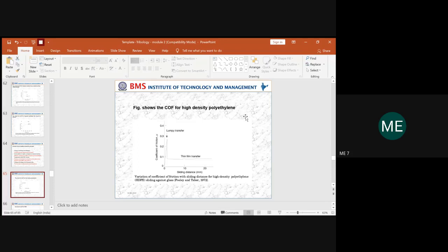The higher density foam will be harder than that of viscoelastic foams, but still the density of it might be comparatively low. And one more thing is viscoelastic foams have more capability of energy absorbing behavior than rigid or semi-rigid foam. So based on the requirement, you should be able to select the polyurethane foam of higher density or lower density.